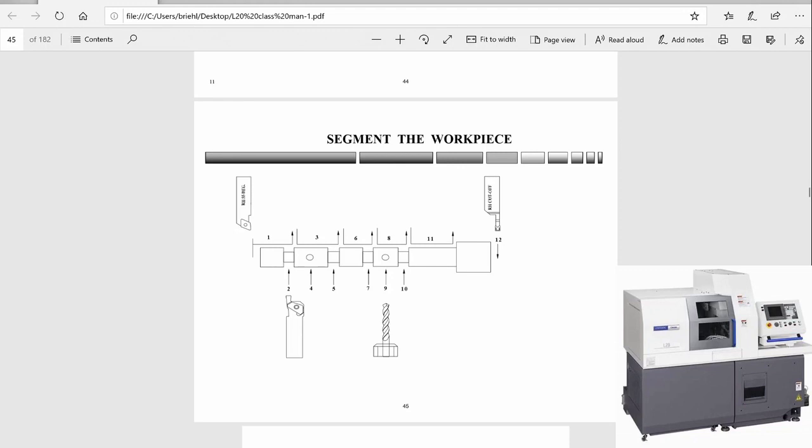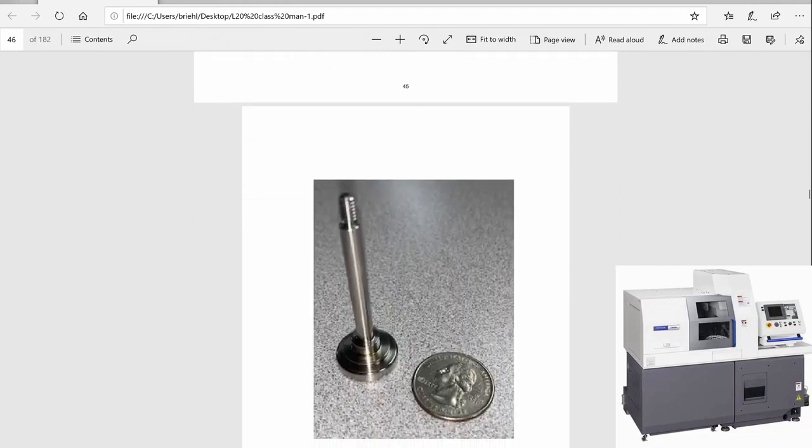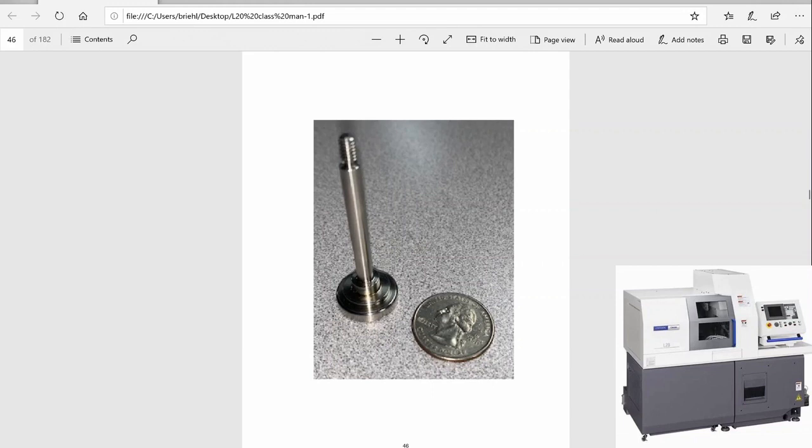For this reason, most parts with multiple features need to be made in segments to allow for proper guide bushing support. However, Swiss-style sliding headstock machines are designed to take cuts up to 300 thousandths per side and still maintain a 32 finish. The part shown here was made from 7/8 stainless steel. The long, slender diameter is 3/16 in diameter and was cut in one pass with the use of high-pressure coolant.